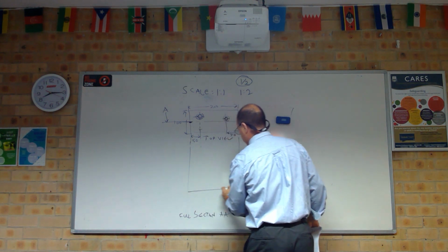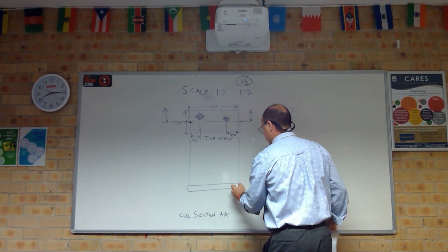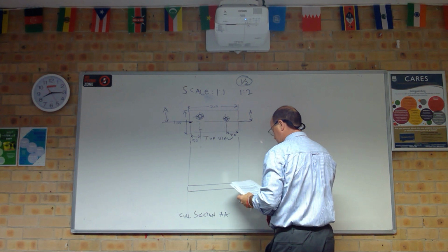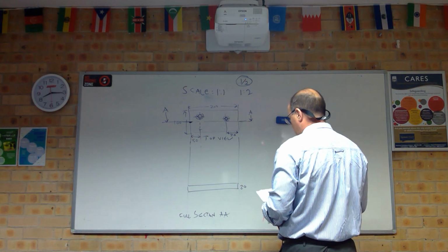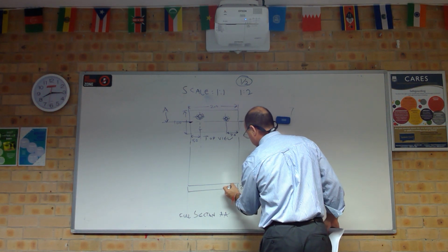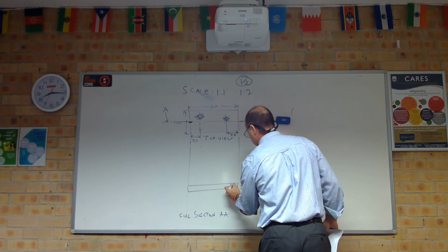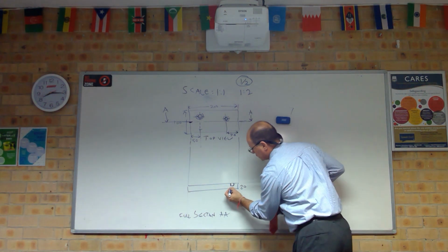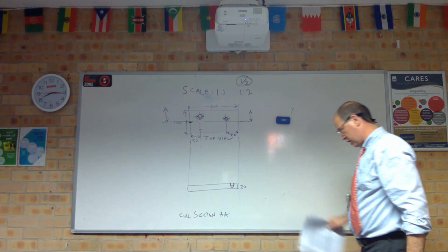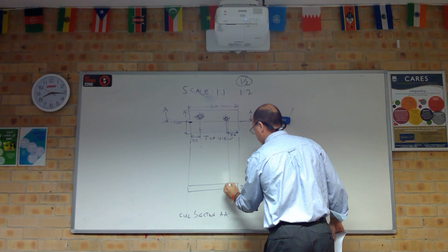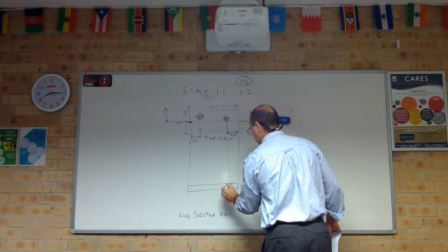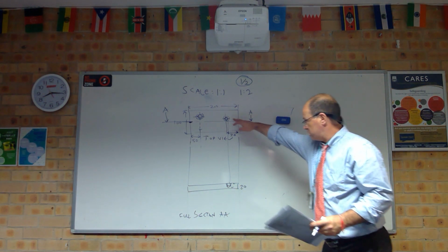So now we know that our block has a thickness of 20 mils. And we said that our tapped hole is going to be going down 100 mils. So we come down with, we'll have 100 mils of thread. And then of course, at the bottom of the hole, we have our triangle. That's our blind hole. And it would have to line up, so I've already done it in the wrong place. It would have to line up with where it is on this diagram, okay?